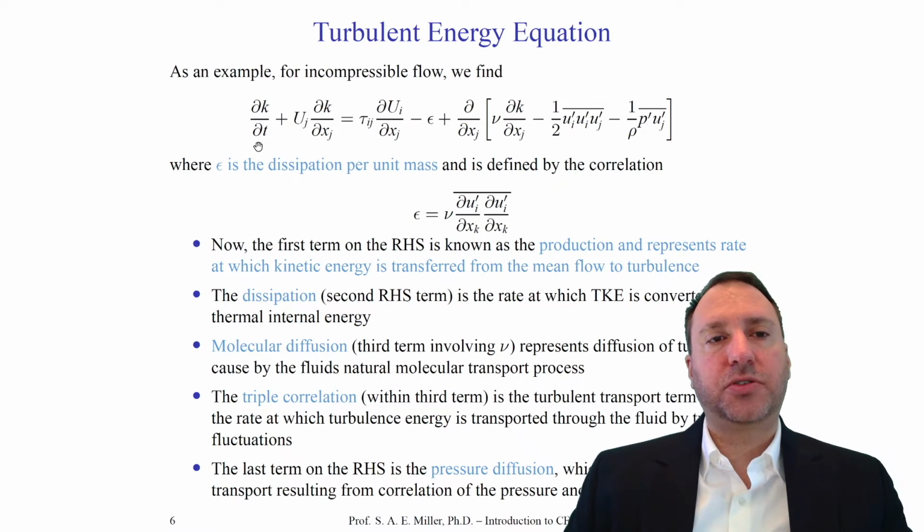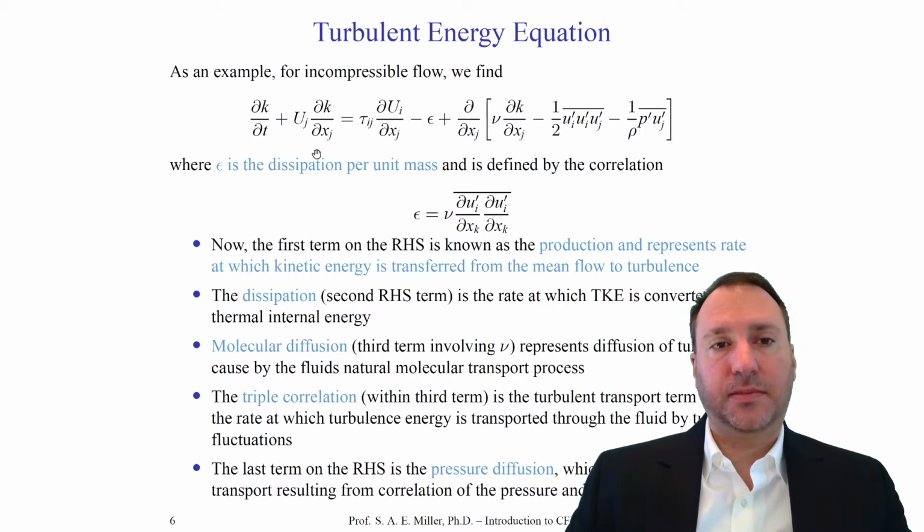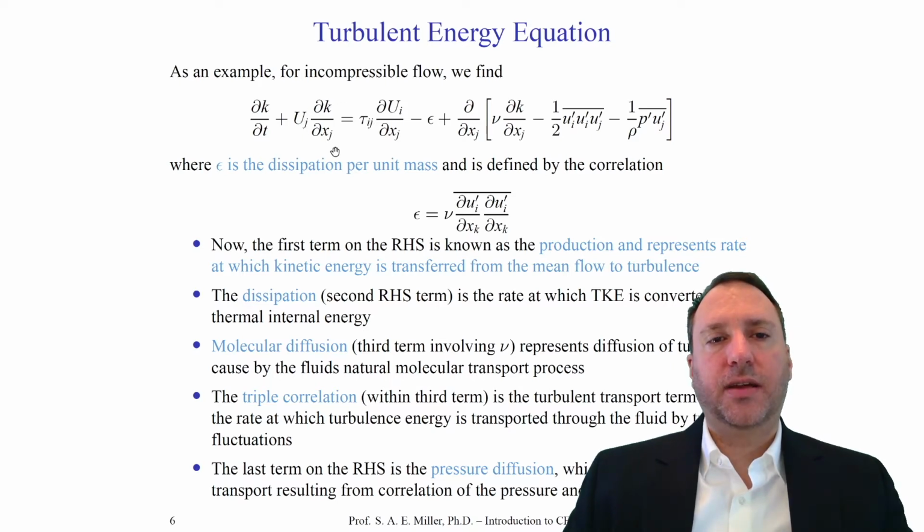So that's a partial derivative. It's an unsteady equation by definition. There's also a compressible form, which of course has a factor of density in it. The second term is like a convection term, and this would go as capital U. Remember, that's the average velocity at some point in space, times the partial derivative of TKE with respect to x, y, and z direction.